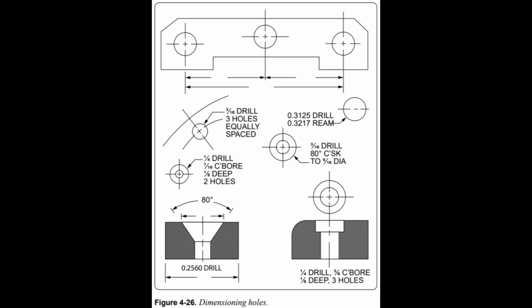A positive allowance is indicated for a part that is to slide or revolve upon another part. A negative allowance is one given for a force fit. Whenever possible, the tolerance and allowances for desired fits conform to those set up in the American Standard for Tolerances, Allowances, and Gauges for Metal Fits. The classes of fits specified in the standard may be indicated on assembly drawings.